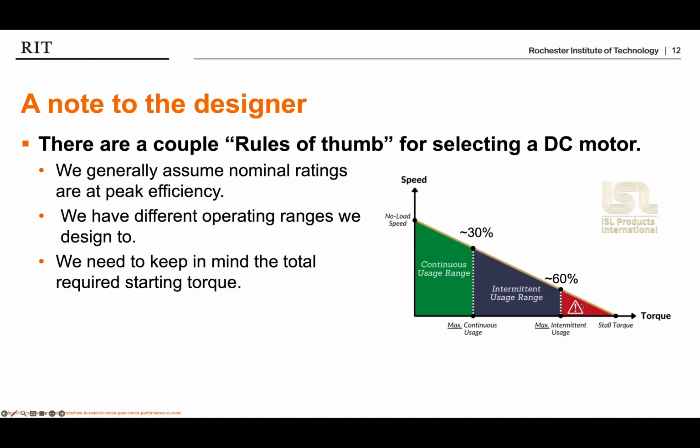I'm heating things up, I'm stressing components, and I'm getting no benefit. So I would argue maybe a little bit on this side of that 60%, considering peak power is about here at 50, but past the 60% mark, we just consider this to be a no-go area for good engineers. All right, so this is my first rule for designers.